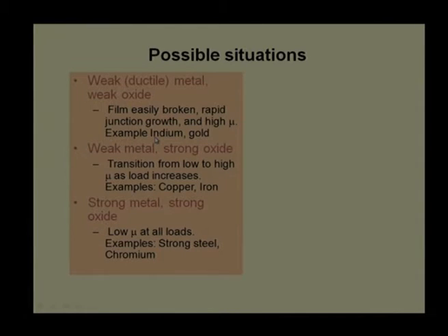A couple of examples which belong to this category are indium and gold. Gold to gold, we found the coefficient of friction very high. Indium to indium, we found the coefficient of friction very high. Even indium versus gold will have a high coefficient of friction.